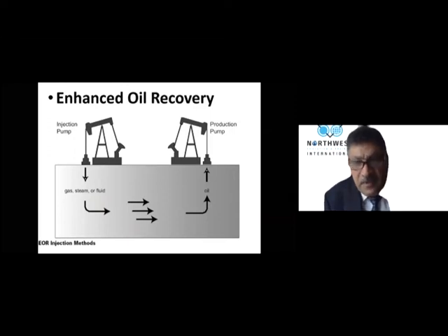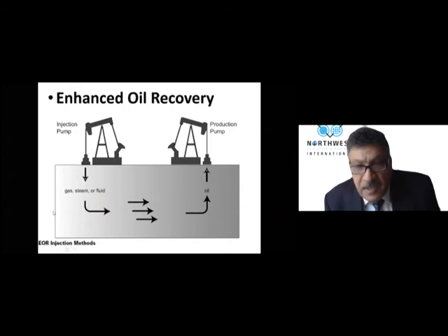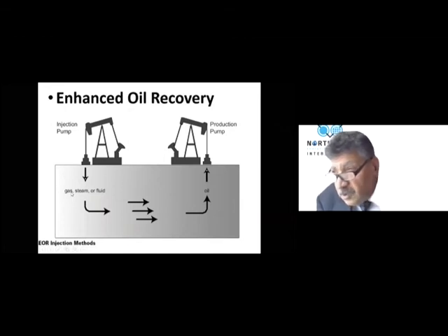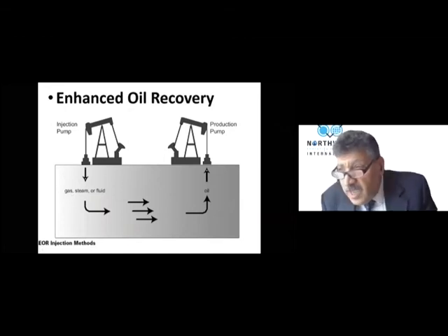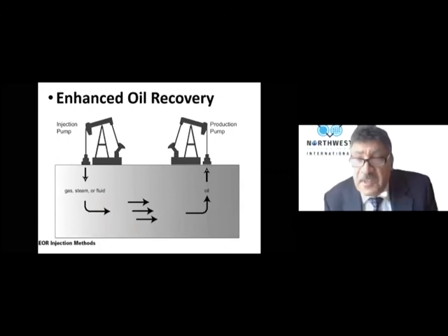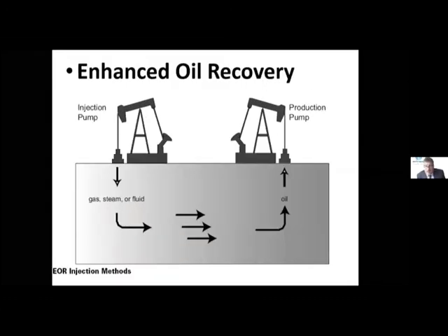And the principle of it, you are injecting something inside the reservoir from one point, we call the injection well, and you produce from the other side, we call the producing well. So the injection, what do I inject? Maybe I inject gas. What's gas? Could be nitrogen, could be CO2, could be LPG, propane, and butane. It could be natural gas, methane. So that's the meaning of gas. The gas is a general word here.